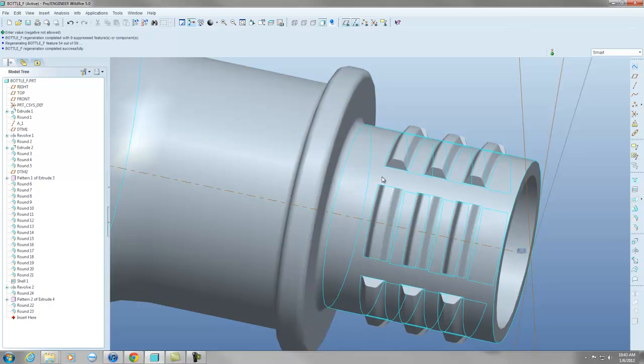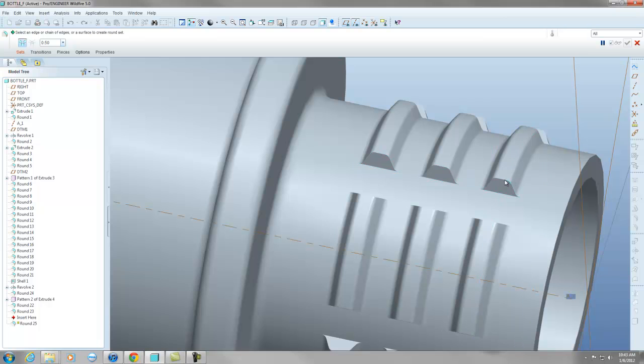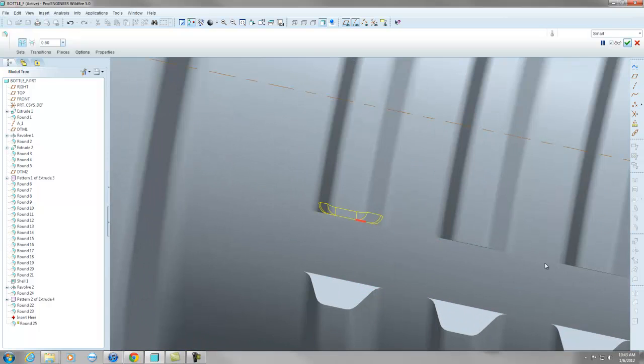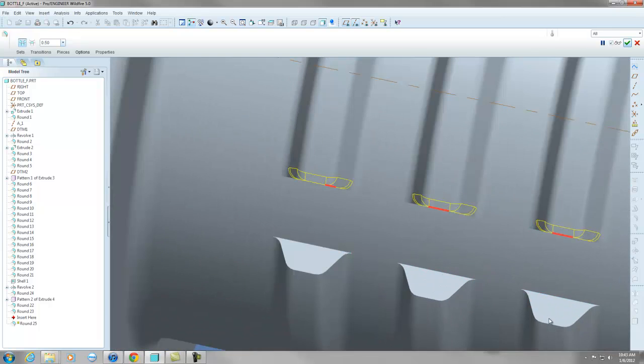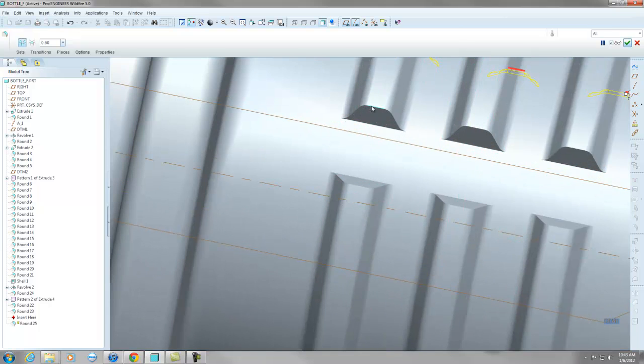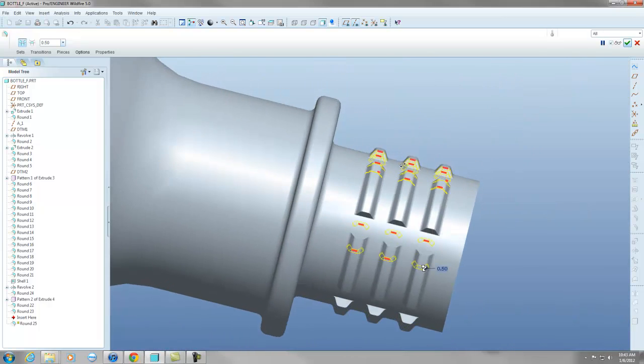Now if you go over here to your tree and you drag your insert back down, it gets you back to where you cut it after, and then I have to blend these because when they're this small, guaranteed it's all gonna be blended because the mold can't keep them sharp. So this is going to take a second, and you don't have to do this.